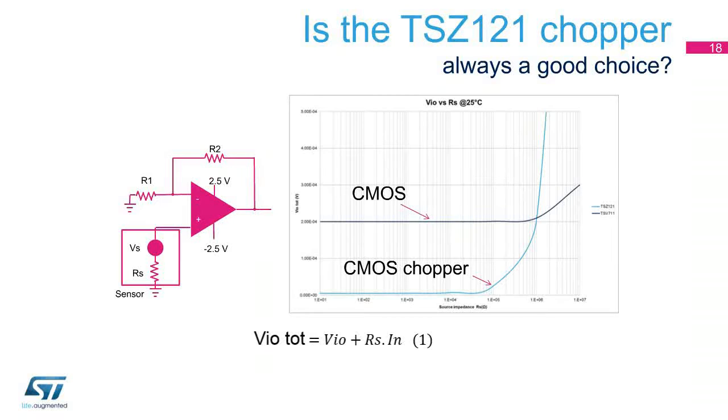It is hard to find op-amps that can be used across a wide range of source impedances, for example 10 ohms to 10 megaohms, and still achieve DC precision. A comparison of the state-of-the-art DC specifications of CMOS and precision chopper op-amps is shown in the following graph.